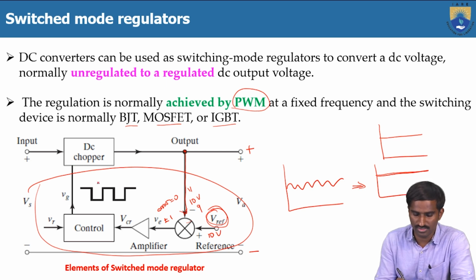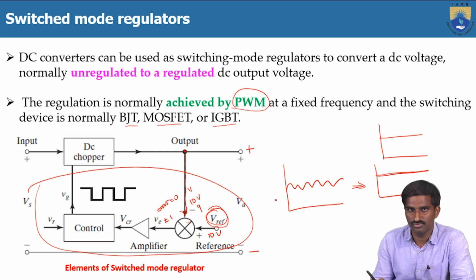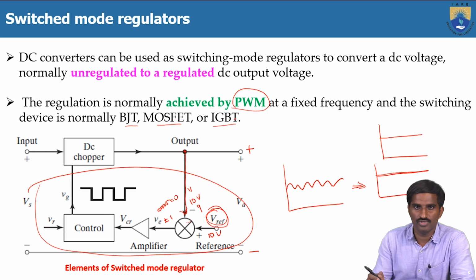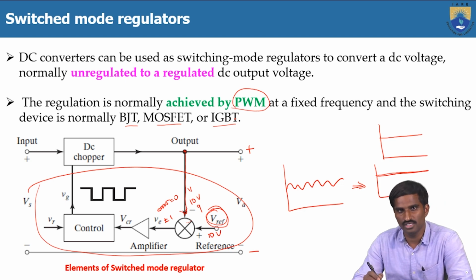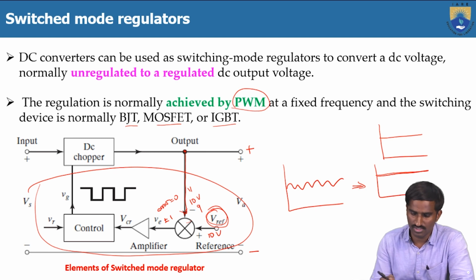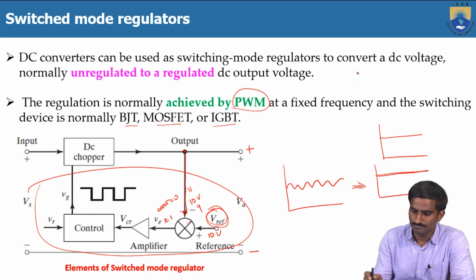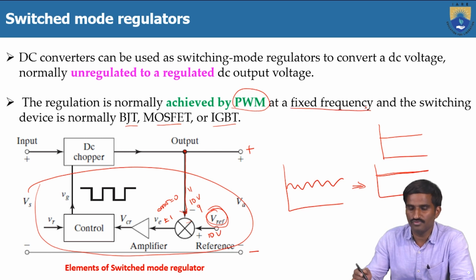Suppose, let me consider, here we are using a PWM inverter. So for that, as we know how the PWM technique will work, pulse width modulation: there one is a reference signal and a carrier signal. By changing these signals' amplitude or the frequency, of course, anyway here we mentioned it is at constant frequency, which means at a fixed frequency.